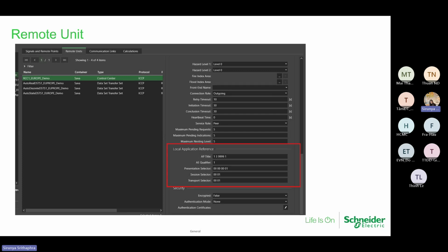What about IEC 104? What's the maximum communication links for an RTU? Normally I saw it's just one, but sometimes we can see 2. I never saw 3 or 4 before. So you need 1 or 2 links for IEC 104. Yeah, I think they're asking about IEC 104, right? Normally at 104, I have seen systems with 2, but not more than 2.